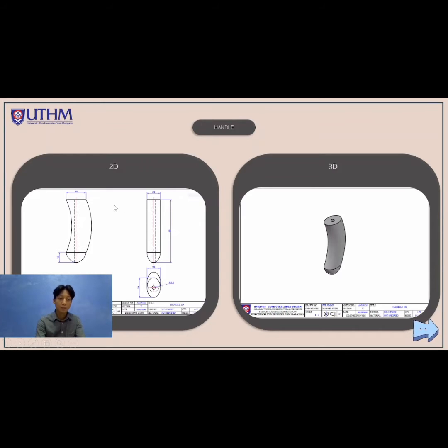And then for the bottom parts here, we make another ellipse using the ellipse center command with 10 millimeters from center for the first axis and 7.5 millimeters from center for the second axis.